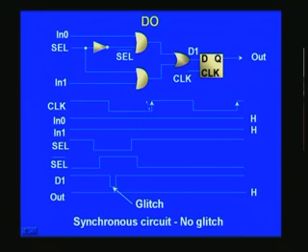Frequency operation is governed mainly by the total delay that you encounter in a combinational circuit, and if you take this into account, then you can always condition your whole circuit in such a fashion that whatever glitch appears will be ignored, and only the steady state value is registered.